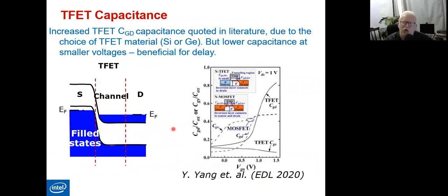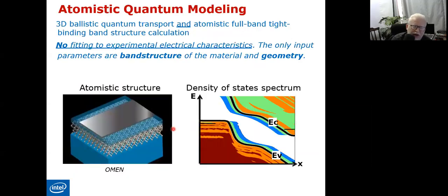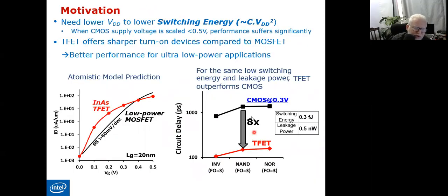And of course, as usual, I believe you are used to seeing this slide in any lecture, which is the capacitance effect. Again, in any MOSFET, in any transistor, or maybe in any semiconductor device, we have what we call the parasitic capacitance effect. And by the way, the parasitic capacitance effect is an extremely important parameter in calculating what we demonstrated in the first slide, which is the delay. Because simply delay comes from charging and discharging, which is the capacitor's role. Whenever you have a capacitor, then you have a charging time and a discharging time, and this is a main factor in the delay.